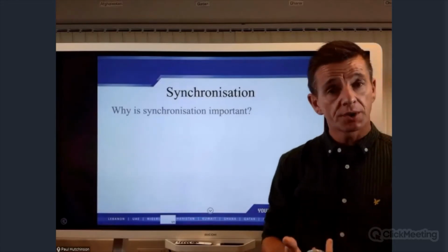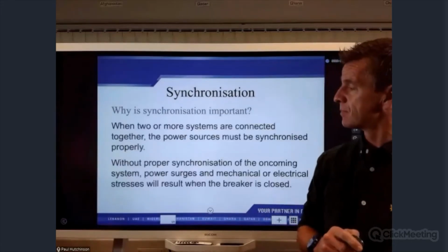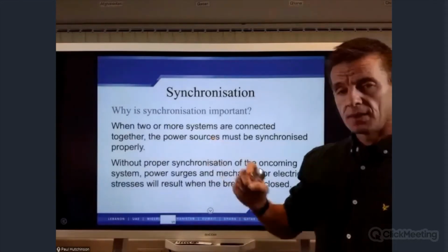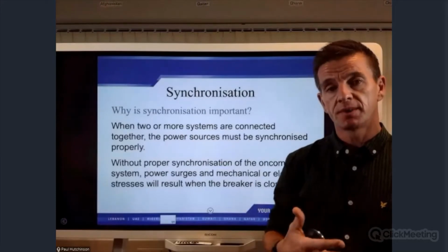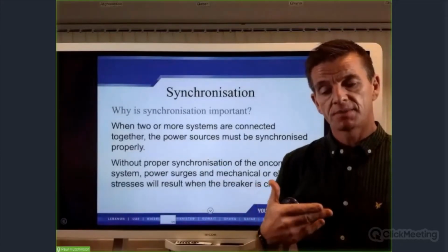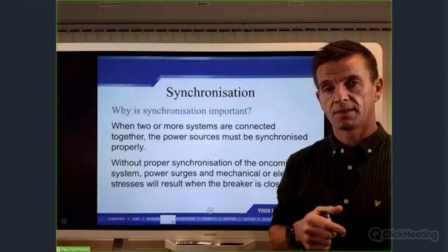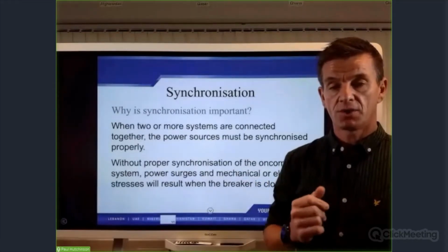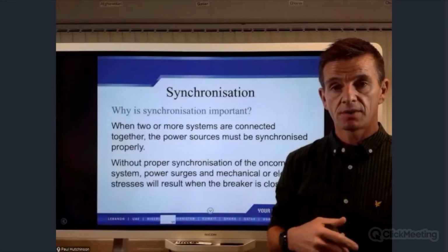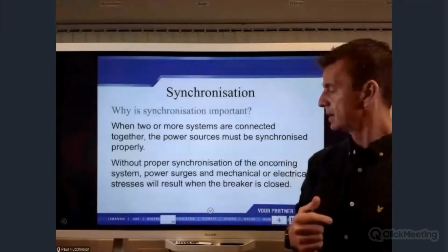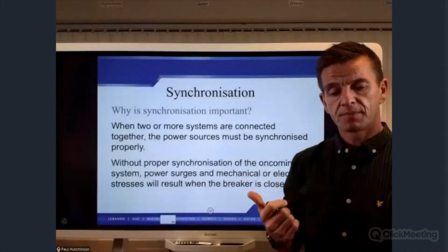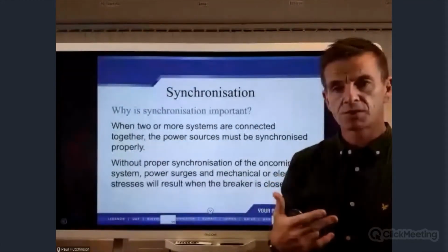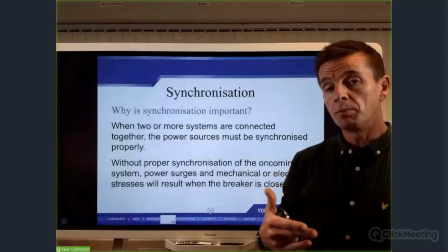Why is synchronization important? Well, as we know, when we bring two or more systems together, it's important that the synchronization is correct. If it's not correct, we can see problems. It can result in mechanical stresses, electrical stresses, power surges, causing major damage to one or both of the systems.